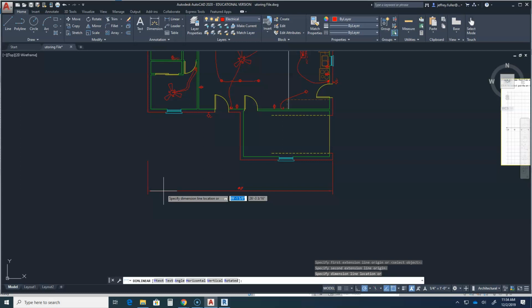So what I'm going to do first is hold the shift button and type the @ symbol, and then it gives me an x-axis and a y-axis. That's what those two boxes are right now. Where it is highlighted in blue, that is my x-axis. So I'm going to type 0 there, and then tab over to the y-axis and type -8 feet. And that places that line 8 feet from the structure.